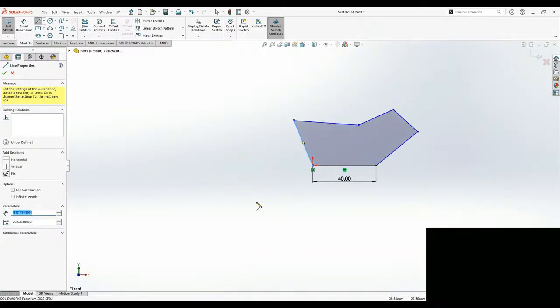The second rule of your sketch workbench is that you should always try to create a rough sketch of whatever the geometry or drawing you have. Don't simply go ahead with the dimensions. Okay, do this much and define the dimension. Don't do that. What you do is you first cover everything with a draft sketch. Okay, now I did the same thing. Now, let's say this is done.